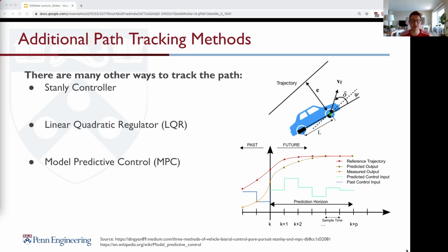And the other error is the so-called heading error, which means the direction of the car. And both errors need to be minimized, because then I'm following the raceline or these pre-recorded waypoints exactly. This is another algorithm you can choose and tune, and you will see different vehicle behavior.